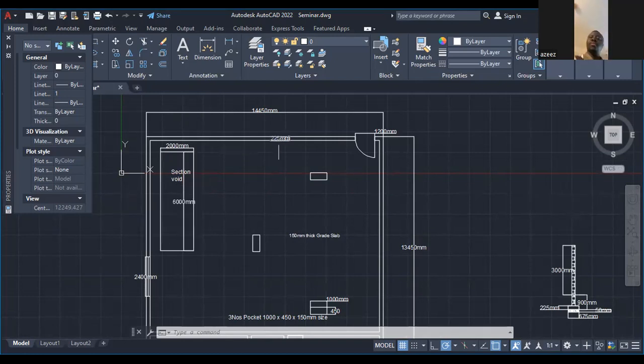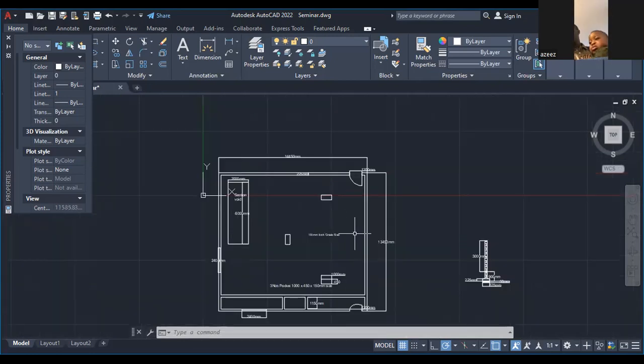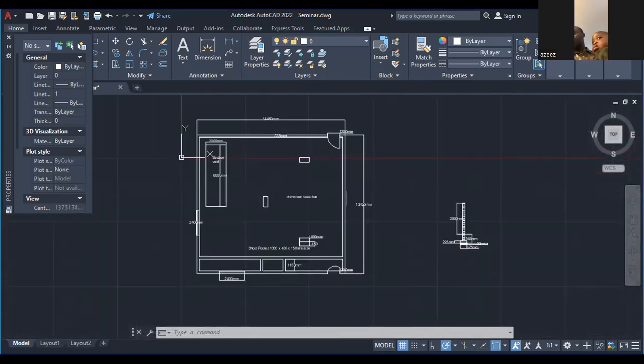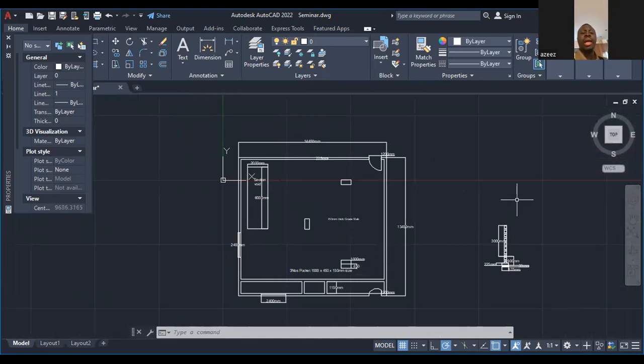So what will be your topsoil? Like 150 mm. The thickness of the topsoil is going to be 150 mm. But what will be your quantity? That would be the length and the breadth, in square meters. But you have to add some extra, because you can't just use your actual working area. I will add the spread like 225. No, just call it extension. Don't call it spread again. We are no more in school.